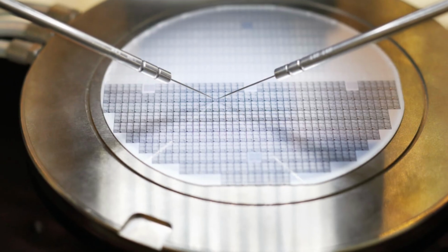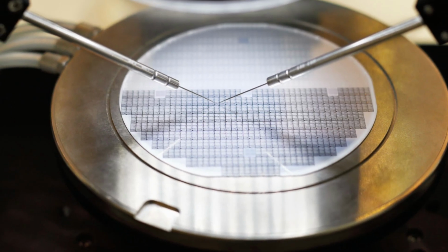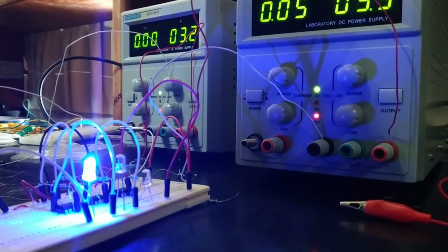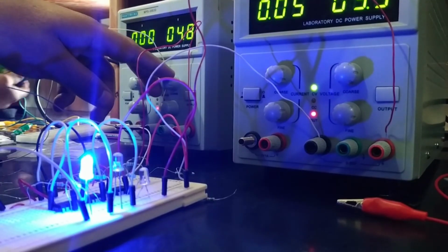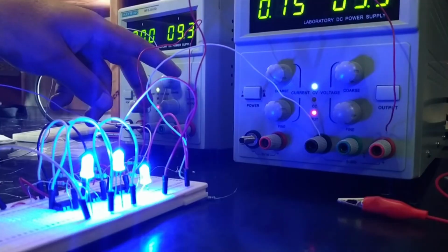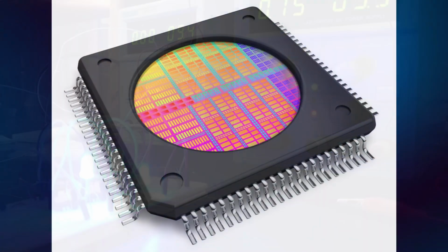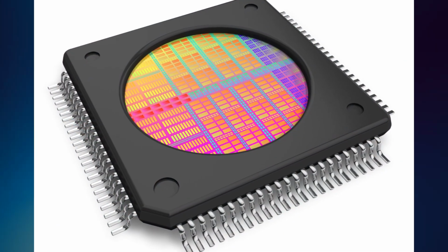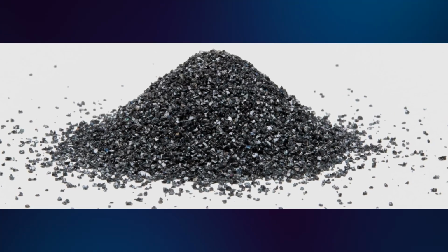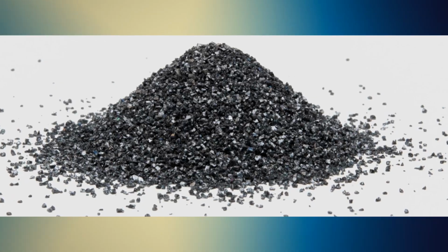Silicon's thermal stability, mature processing technologies, and versatility across various process corners, voltage, temperature, and manufacturing variations have helped it dominate the semiconductor world, despite some limitations like low electron mobility compared to materials like gallium arsenide and lower thermal conductivity than silicon carbide.